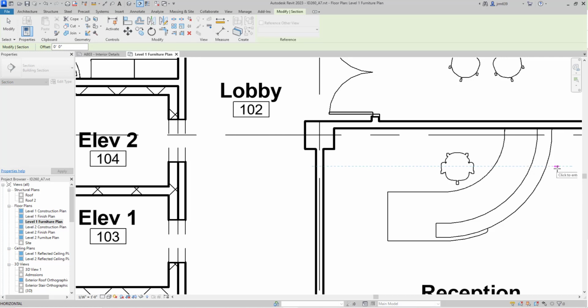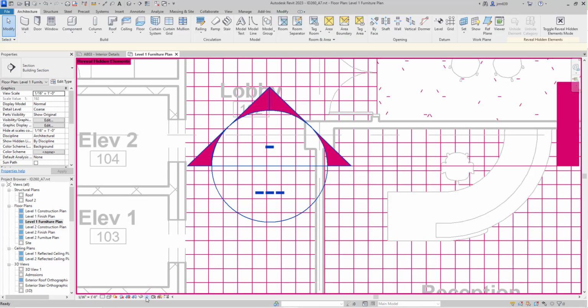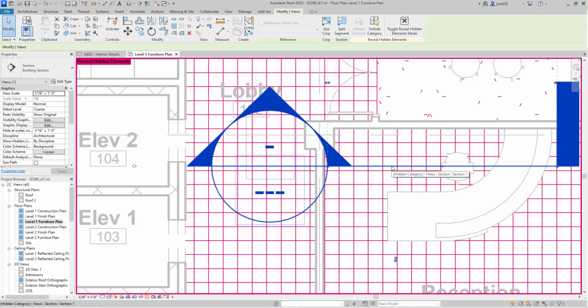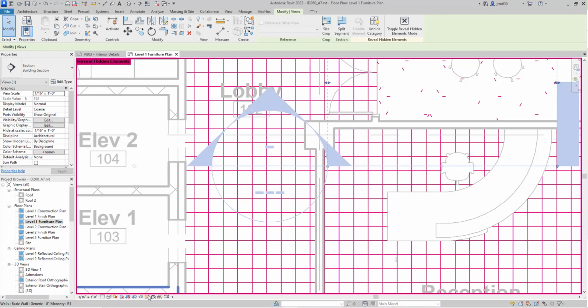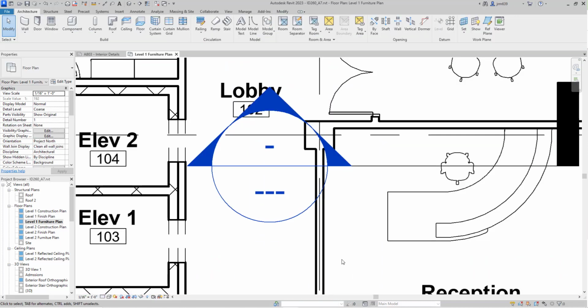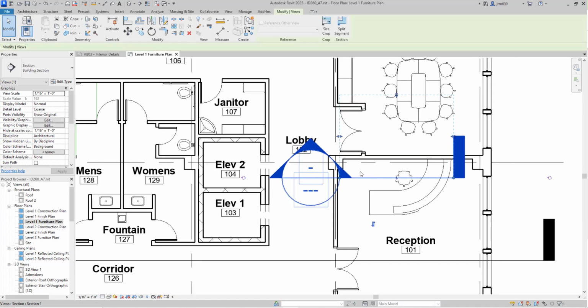So if you want to see that and put it up on the desk, I'm going to create a section. Just kind of a temporary section. It looks like my sections are all hiding, so I'm going to unhide it from the Stranger Things world. That's what I always call the little light bulb down on the very bottom. I'm going to unhide the section by category. Click on that light bulb again, and then I'm going to flip this section by grabbing the bar and then finding the little flip tool underneath and flipping it.